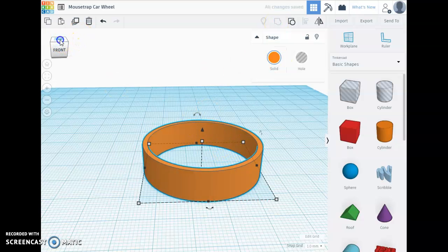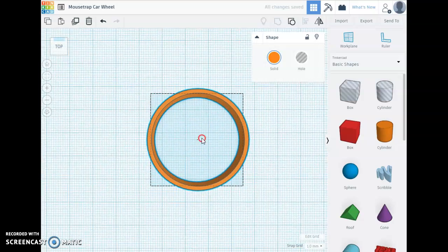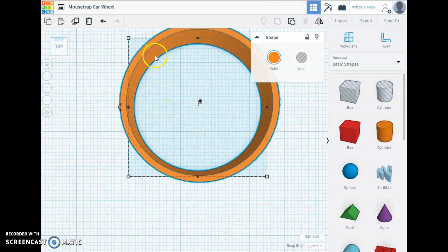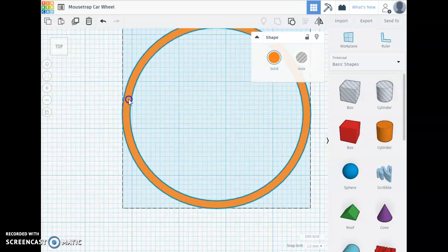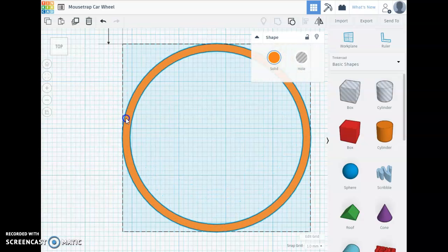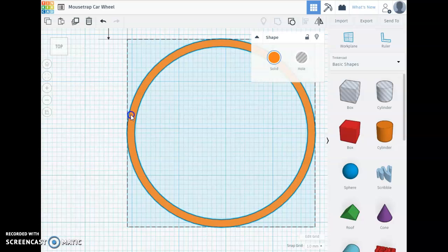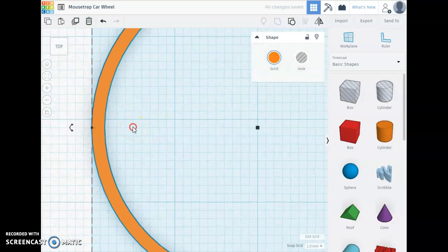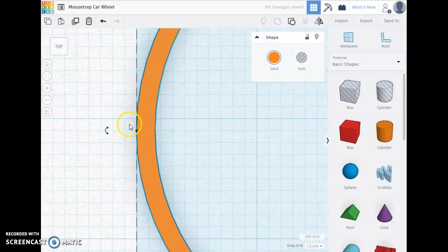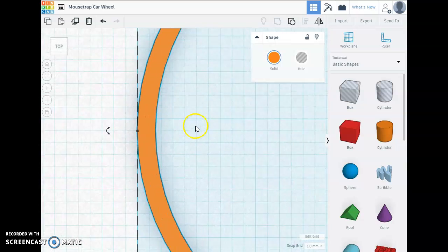Okay, now if I take a top view and I want to move out of perspective view, it's going to show me these edges. If I want to look straight down in a parallel projection, I'm going to switch to orthographic or flat view. I can just use this to test, does it appear based on my grid that I have made this 1.5 millimeters? I would say if each of these boxes is 1 millimeter, there's 1.5. I believe that's come out as planned.